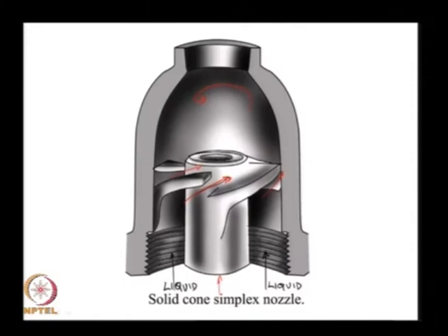Okay. So, not only is this going to create a swirl action, but it is also going to create some liquid coming straight through this way. So, the resulting spray is going to be a combination of a pressure swirl and a pressure jet atomizer, and so therefore, this is essentially to control the spray pattern coming out of the nozzle. The pattern is an indication of whether the drops in the spray are distributed in a hollow cone or in a solid